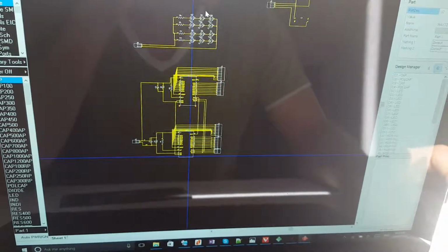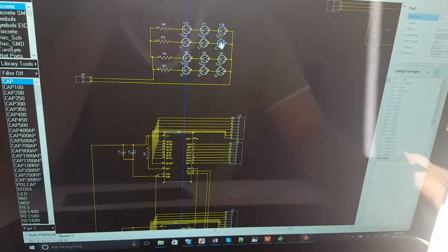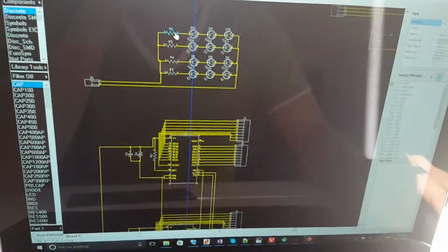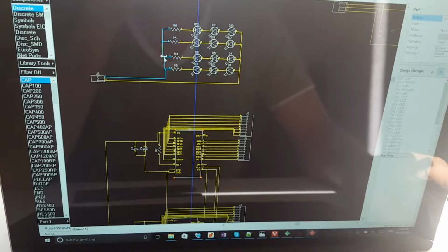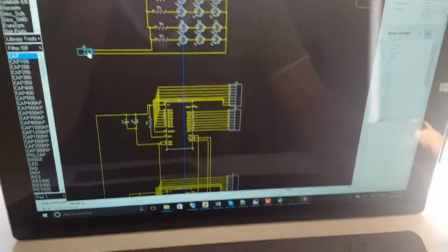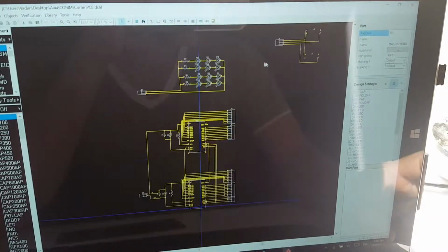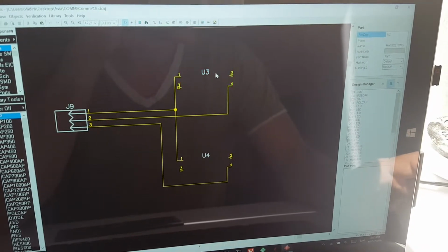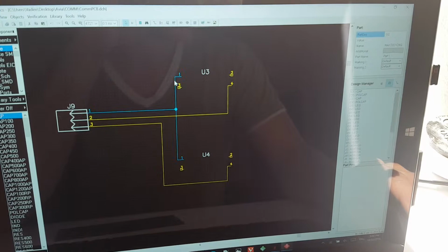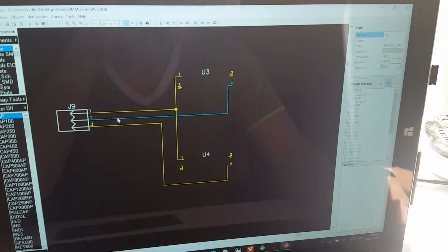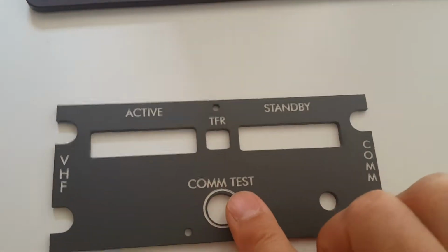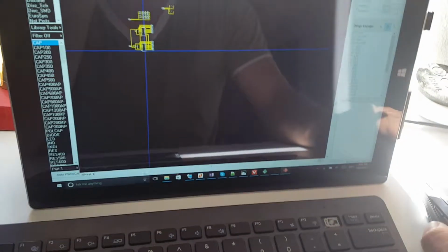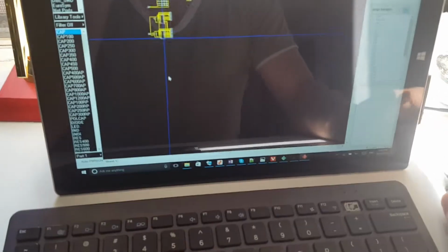There are 12 LEDs for backlight, right there. Groups of 3 resistors to control the current, all parallel to a power connector. And right here we have 2 buttons. The buttons have 4 pins on them, so they have a common pin and 2 individual pins going to every button. Those will be button 1 and button 2. And there we go. This is the schematic.